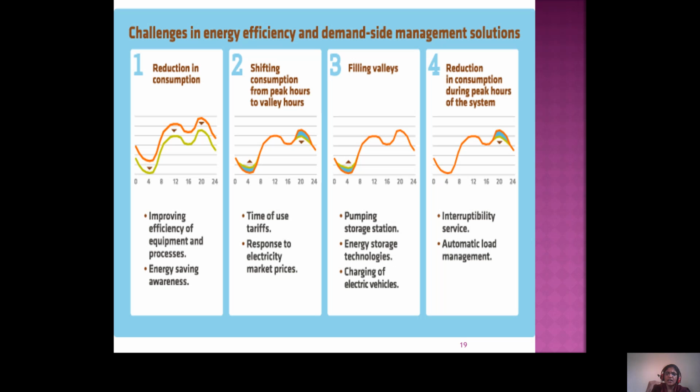The basic advantages of demand side management are better usage of existing generation and distribution, less environmentally unfriendly generation, load matched to the variable renewable energy available, lower generation and transmission cost, lower transmission and distribution losses, reduced spinning reserve cost, and better maintenance opportunities.